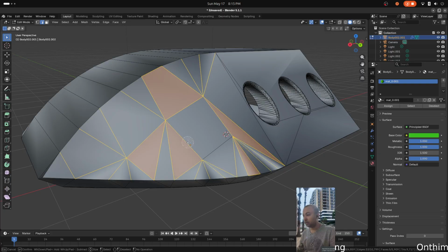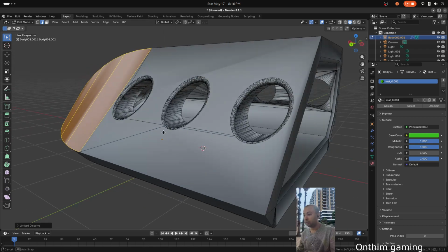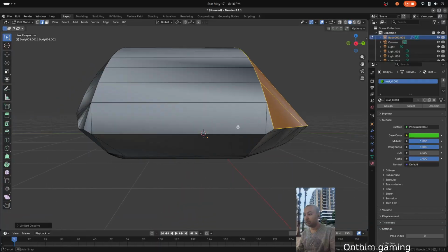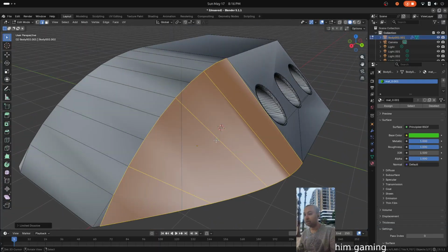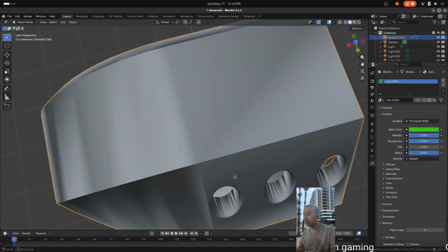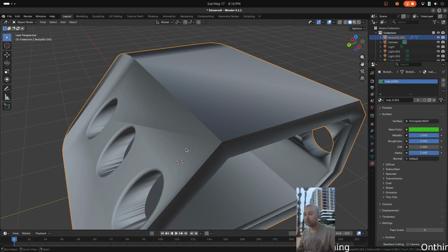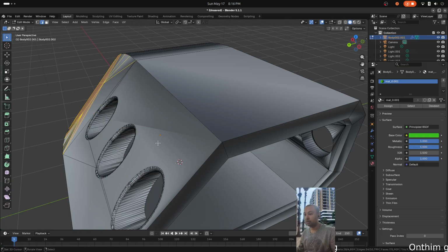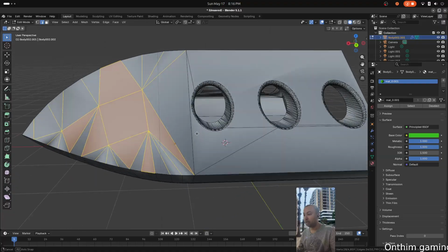Obviously these are not nicely done quads, so I just selected, and let's say X limited dissolve, but maybe it cleans up too much. Now we are losing some of the details, maybe. Not sure. Let's Control Z to undo. But yeah, it maybe can be done.